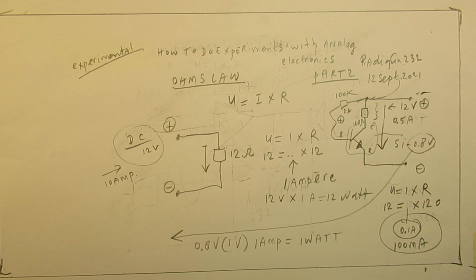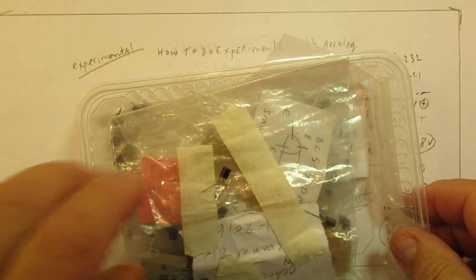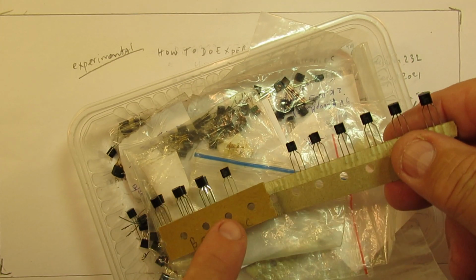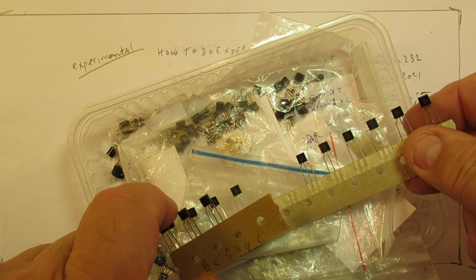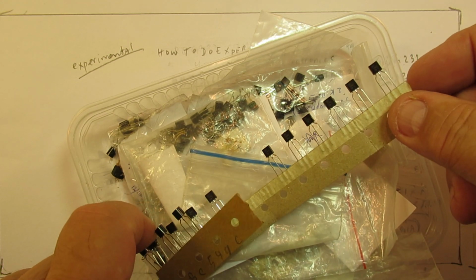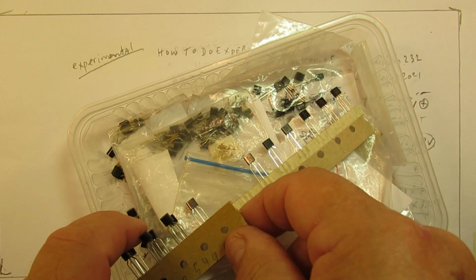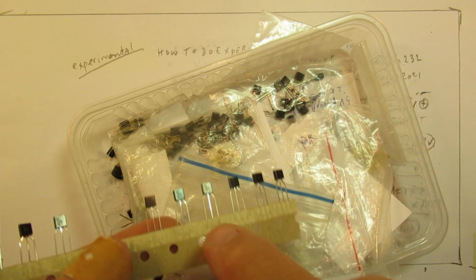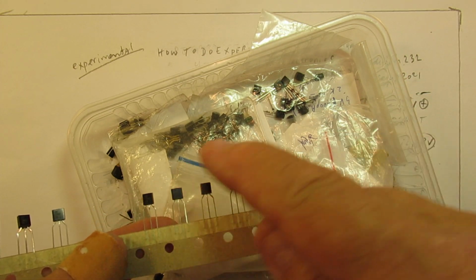That does not seem perhaps much, but I can surely tell that, for instance, the whole bunch of transistors that I have here, they are all small signal transistors, and 1 watt for such a transistor is a lot. It can surely burn out, and you can look for instance to the dimensions of the transistor, how it was made, whether the encapsulation is plastic or metal, etc.